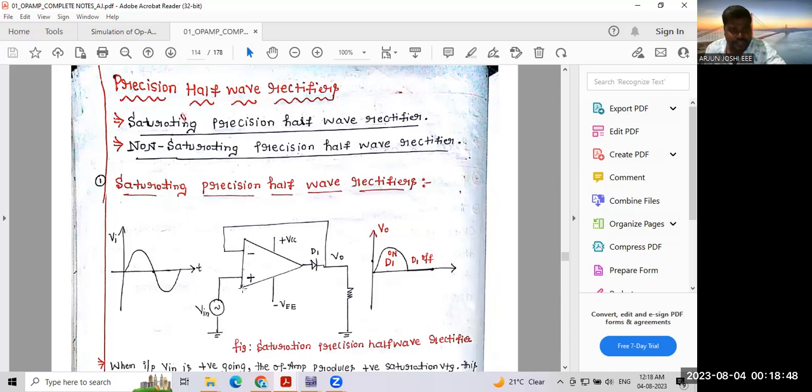You need to observe here. I'm going to give the input signal from the signal generator supply to the positive terminal. Positive terminal is nothing but the non-inverting terminal. When we give positive input, it is going to produce positive output only. That is the beauty of this non-inverting amplifier. And then the inverting terminal I'm going to give to the feedback path. Input non-inverting terminal to the output terminal, that is nothing but feedback.